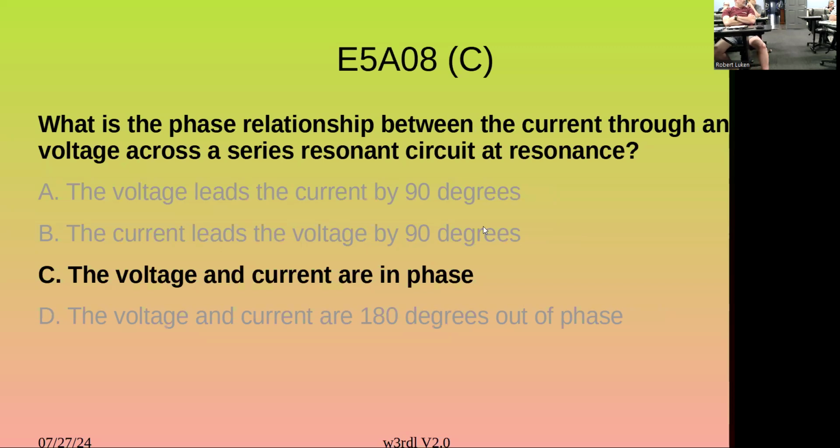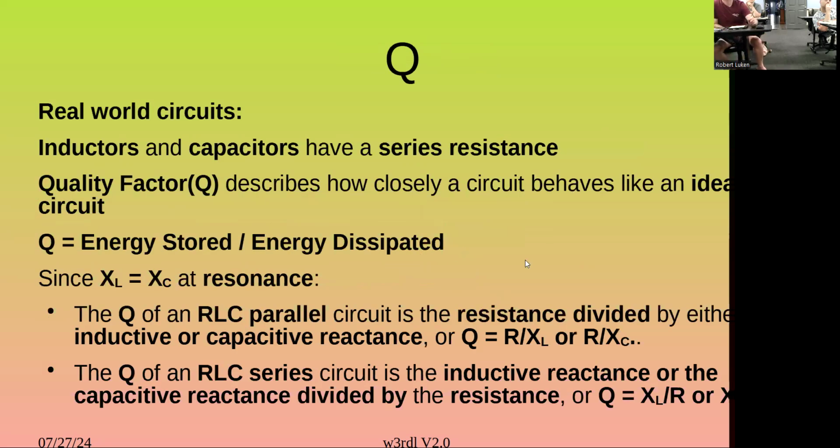The thing I wondered about is when you're talking about the voltage increasing. But that just means they're in phase. The current and the voltage are in phase at resonance, even though the voltage can be more. That's just due to the circulating currents.